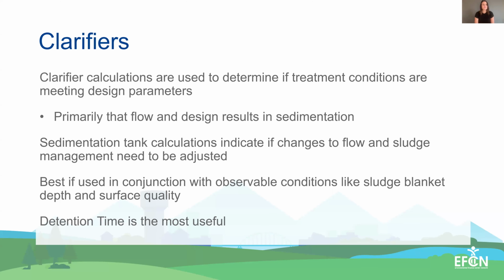Now, calculations for our clarifiers are important because they're used to determine if treatment conditions are meeting design parameters. Primarily, this is to make sure that the flow we have in design will result in correct sedimentation. So we're making sure that there's enough detention time, enough surface area, and enough weir length to treat all the flow that's going to be coming in.